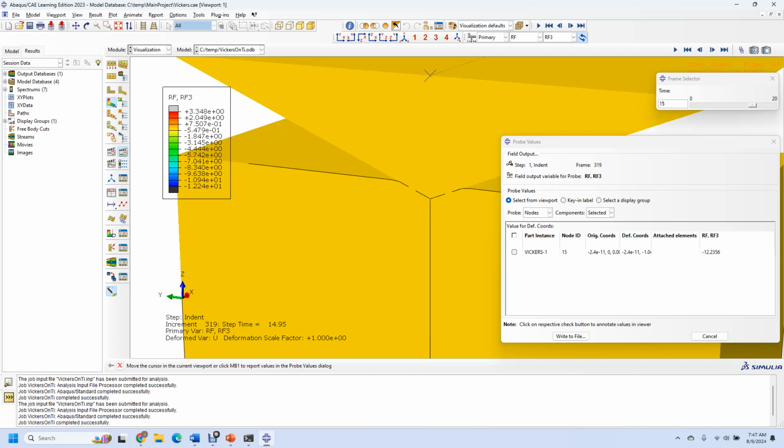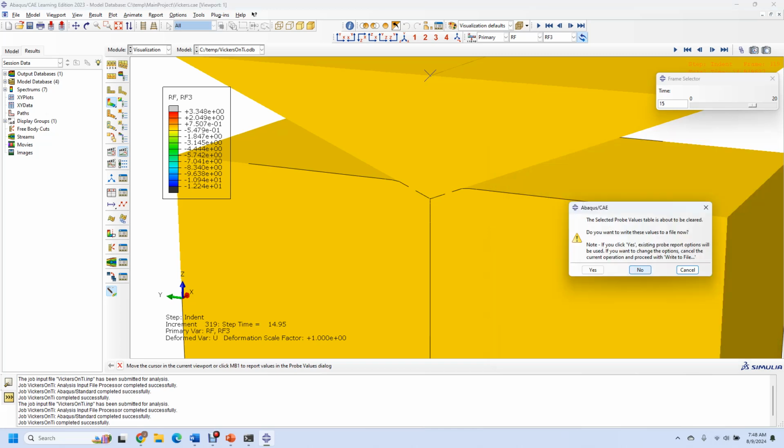However, I think the bigger problem is that the Johnson-Cook might not be the best in terms of dealing with non-spherical geometries. Because when I did the Brinell test, which we'll look very briefly at, it matched very closely with reality. So I think there's geometric factors that probably play into the Johnson-Cook a little bit more than I realized.